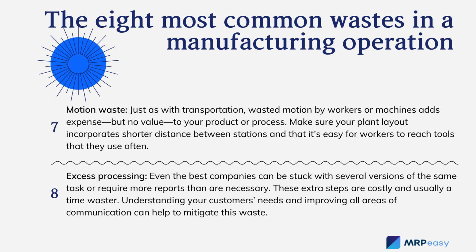7. Motion waste. Just as with transportation, wasted motion by workers or machines adds expense, but no value, to your product or process. Make sure your plant layout incorporates shorter distance between stations and that it's easy for workers to reach tools that they use often.